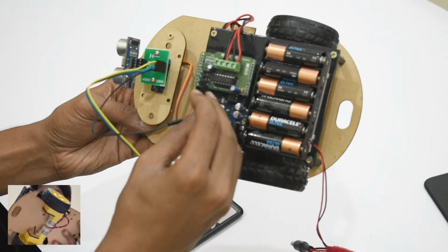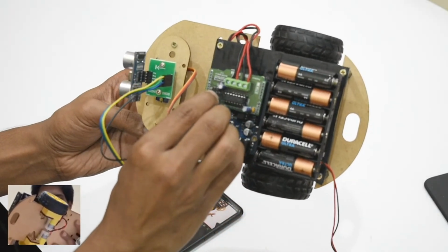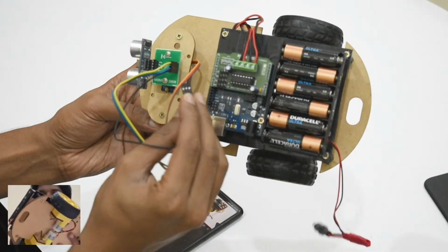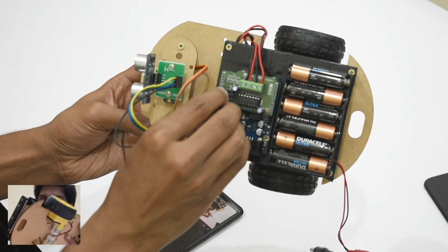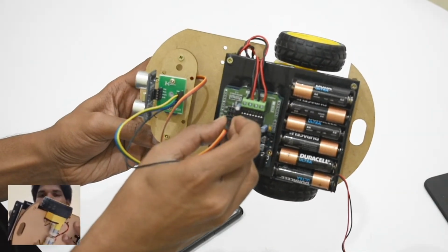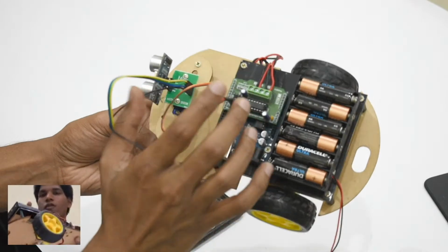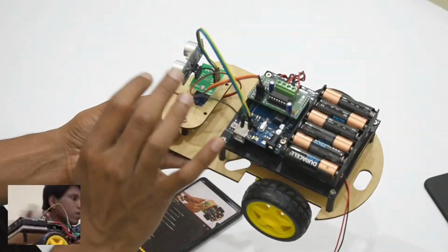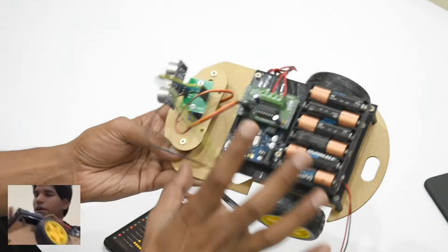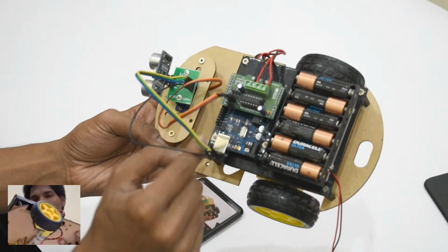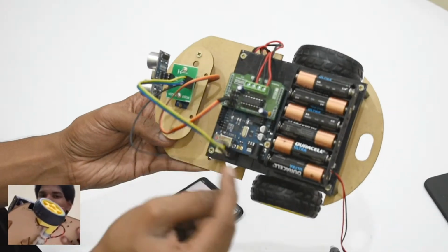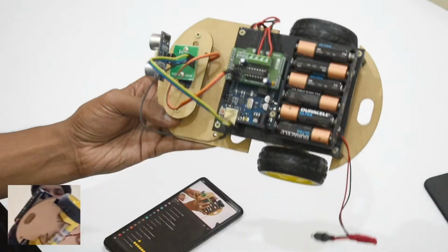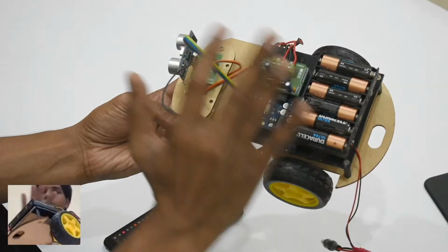Okay, so right now I'm attaching my servo to pin number 9 of Arduino, the data pin of servo to pin number 9 of Arduino, and 5-volt and ground to the 5-volt and ground of Arduino. That's all. It comes in sets of 3 pins. You can just plug it in, just check the pin number in which you're attaching it. So I have attached the yellow wire of the data pin of the servo to pin number 9 of my Arduino. That's all I have done.